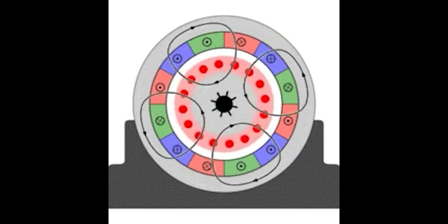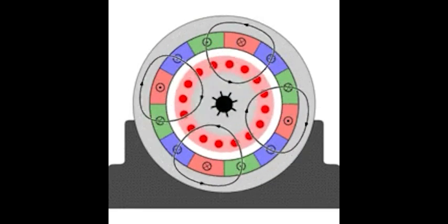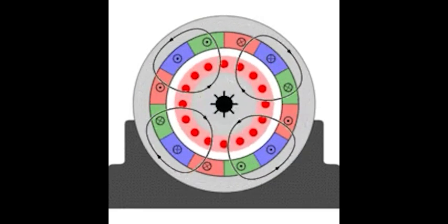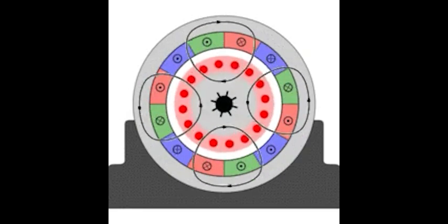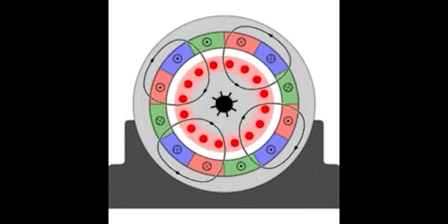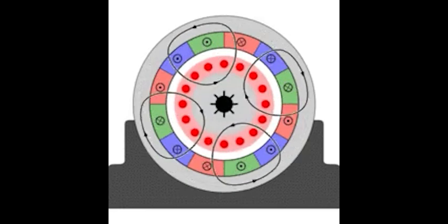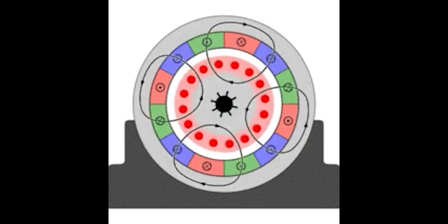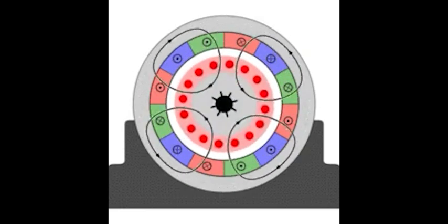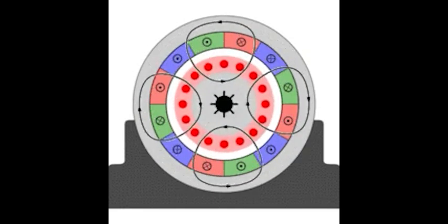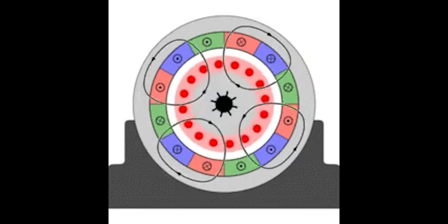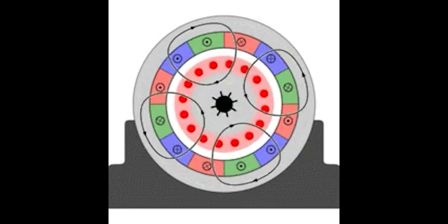The downside here is that the rotor coil must be at least somewhat magnetized for the generator to start up, meaning that the rotor coil must be connected to an external power source to start up, or contain some residual magnetization. The biggest application for these types of generators is in wind turbines, which can be connected directly to the power grid as a way to induce a magnetic field in the rotor when the turbine is spun from rest.